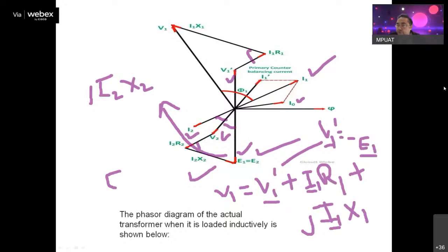Somebody has asked some question. Yes, the main flux, yes, very clear. This primary counterbalancing current is there in order to maintain the main flux constant, उसको phi रखना है. उसमें जैसे phi2 ऐड होता है वो डिक्रीज हो गया, तो प्राइमरी करंट ने कहा चलो मैं तुम्हारे लिए युद्ध लड़ता हूं और ये phi2 को कैंसिल करता हूं, तो नतीजा हमारा मेन फ्लक्स phi कांस्टेंट रहा. इज इट क्लियर? मेन है कि phi को कांस्टेंट रखना है.